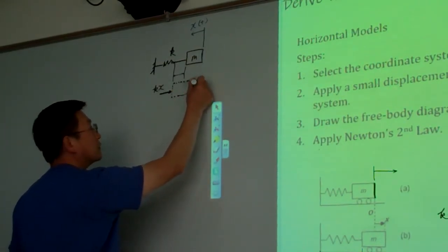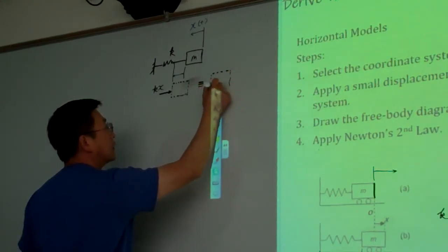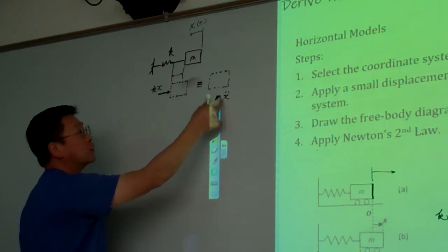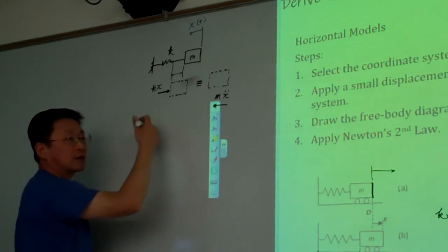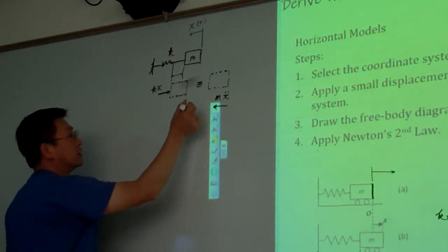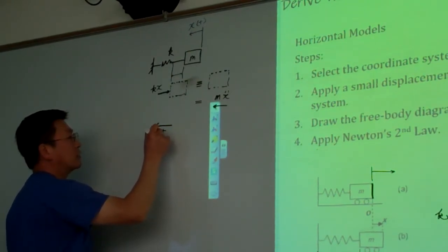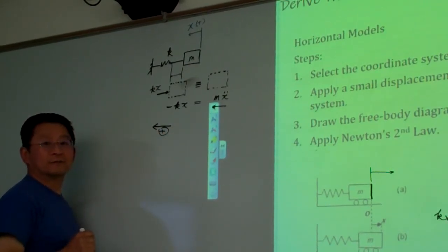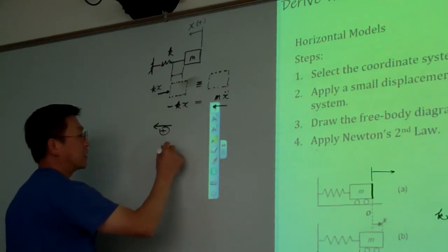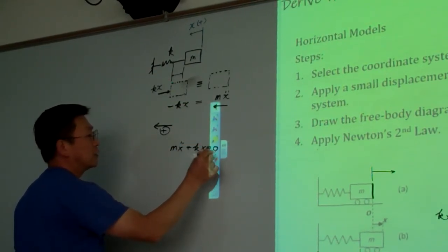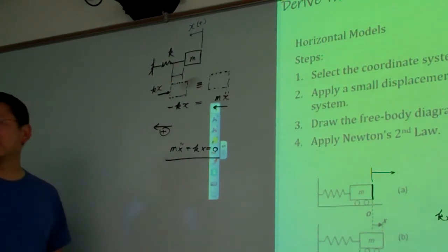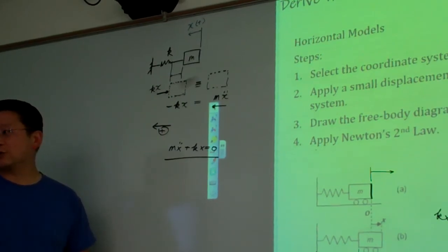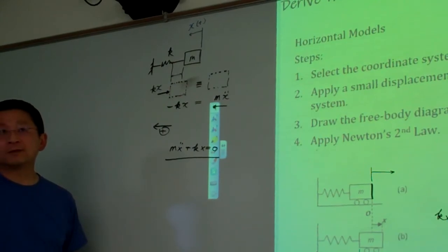Okay. Now for this case, it is equivalent to using Hooke's law and Newton's law. This is m x double dot, the inertial force, and to follow our sign convention it should be moving in that direction. In terms of formulation, if I pick the sign convention with positive going that way, the spring force becomes negative. So using this, you can see m x double dot plus kx equals 0, the same thing as we have here. That is what I mean: if you select your degree of freedom and define a direction, and keep all the calculation and formulation consistent with your choice, then eventually you should have the same expression as everyone else.